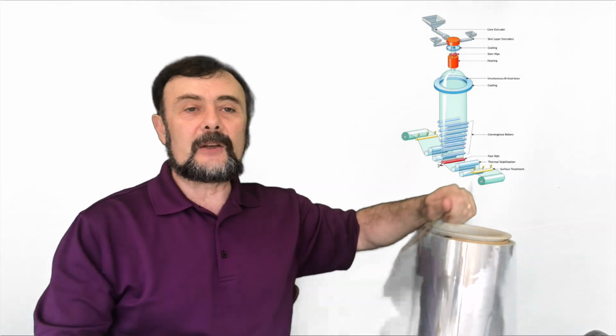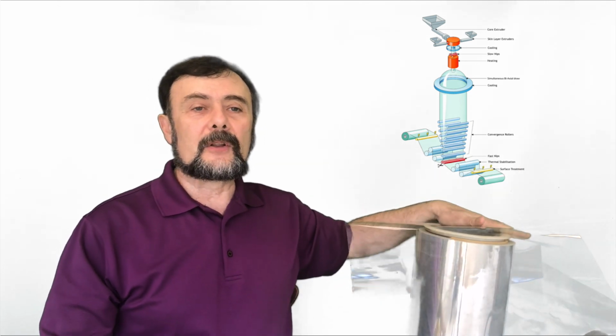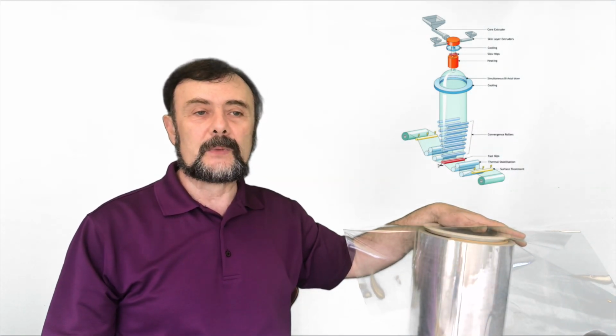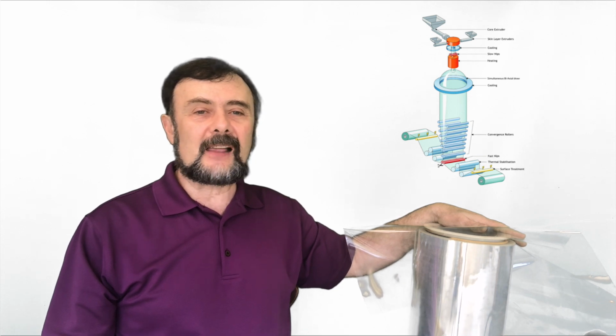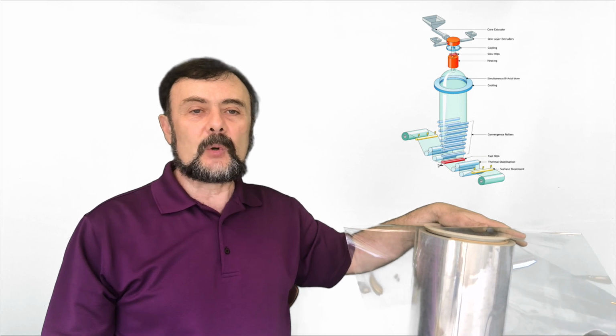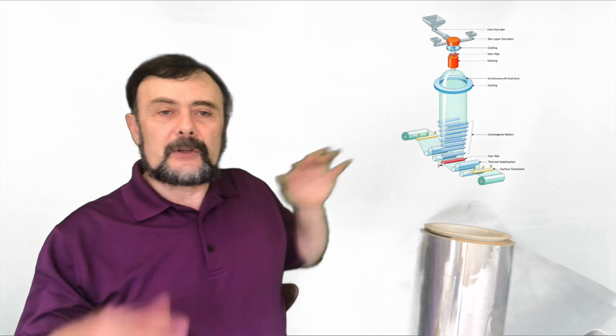The film was made using a bubble process, where at the top of a tall building there were large extruders melting and filtering plastic and pumping it through a round die to make a continuous plastic tube. The tube is frozen, reheated with infrared heat, just enough to soften the plastic so it could be stretched. Yet it is cool enough so the molecules are still entangled with each other, so the bubble stretched.